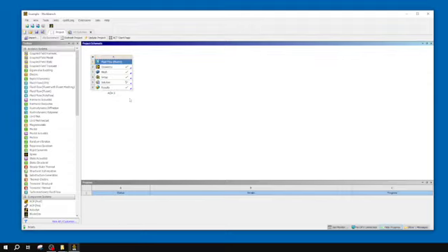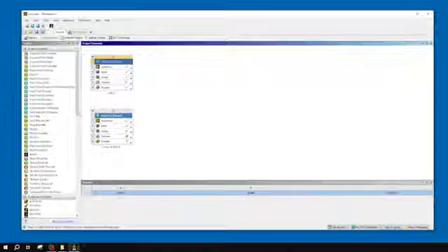And then I'm going to right click on Fluid Flow and duplicate it. After a little bit, it'll make this entire cell block a second time, called either copy AOA 0 or AOA 0 copy of AOA 0.